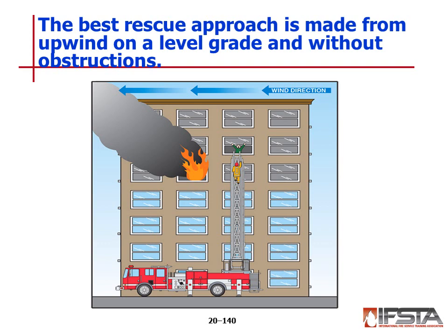The apparatus should be parked so the aerial device turntable is upwind of target. If approach is made from downwind, the aerial device may be enveloped in smoke, exposing personnel to toxic smoke and inhibiting vision.